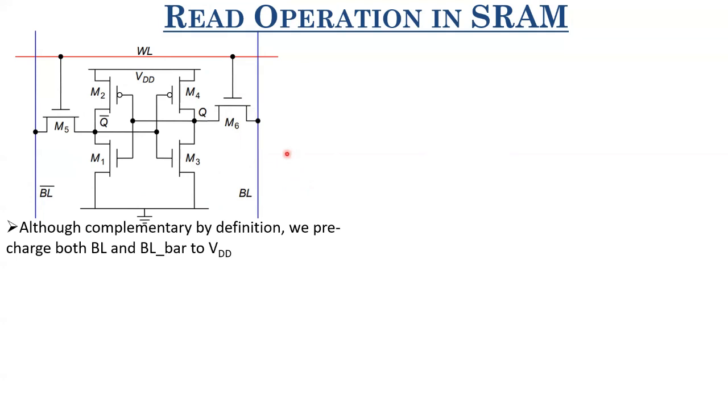On top of it, you also have this interconnect wire capacitance, right? Since this is a line, this line will have an interconnect capacitance, and that interconnect capacitance will also be added to this CBL. What apart from that? So apart from that, we saw that for all these bit lines, there was a sense amplifier which was connected to these bit lines, and that we told was helping in generating rail-to-rail swing and improving the speed, read speed.